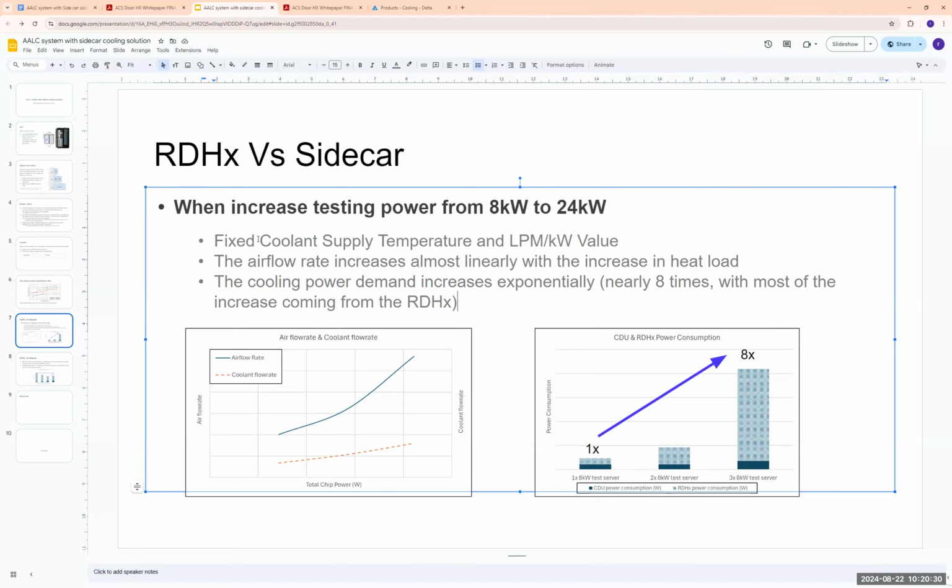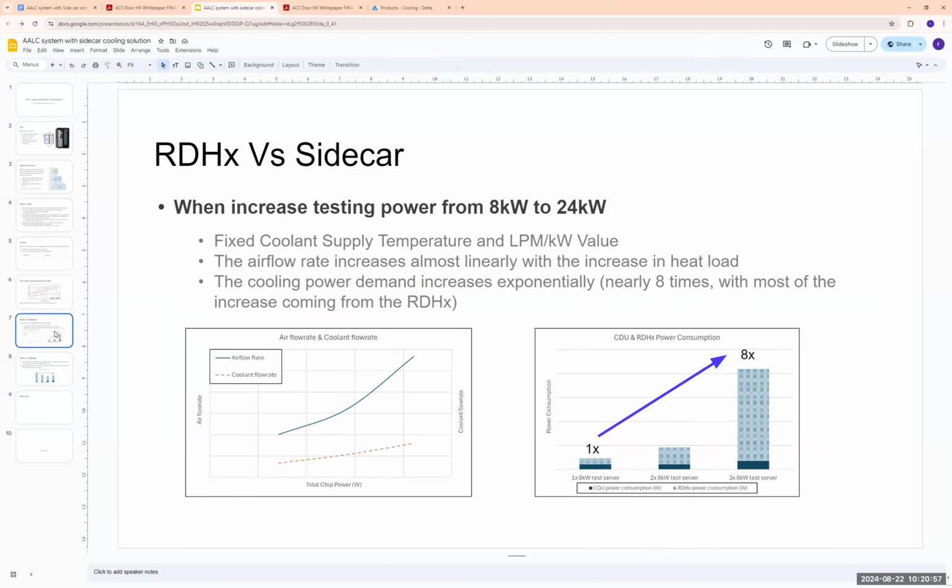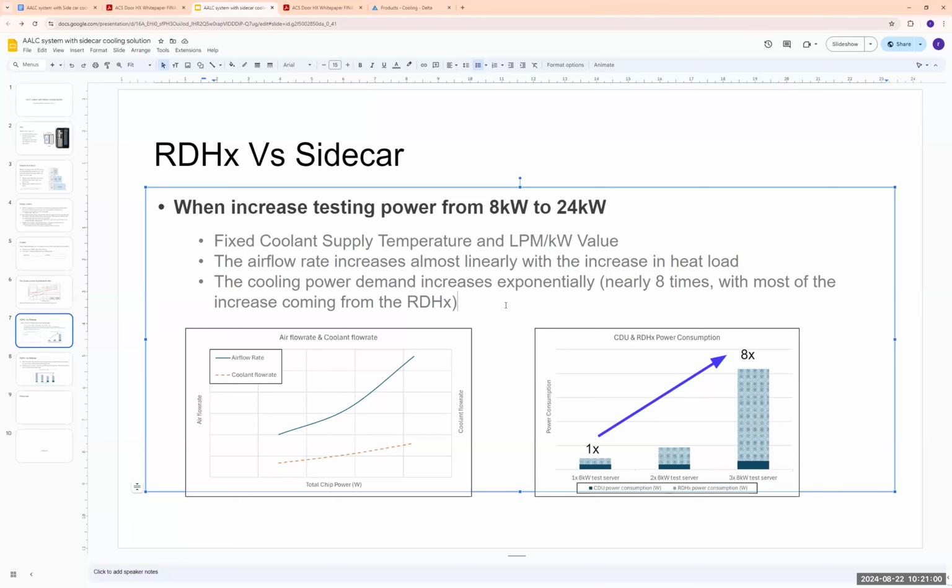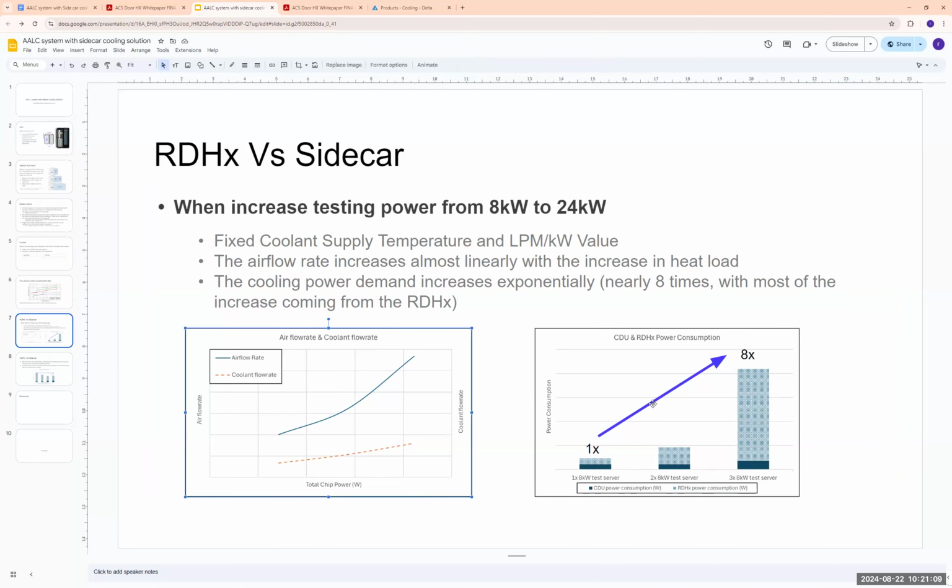Yeah. Mark. I think this result only transfers the liquid to the cold plate. So most of the power is cooled by CDU. Is that what you are asking? Yeah, it's for a server. Are you cooling DIMMs, GPUs, FPGAs, Southbridge, CPUs, everything like that, and then there's just a little bit of glue logic left over that's air cooled. So it might be 10% or something like that of the total.